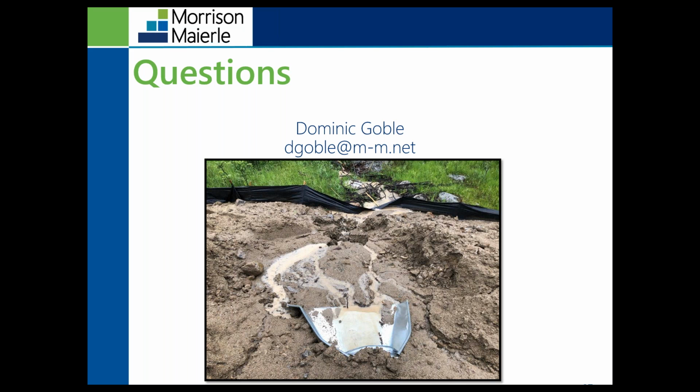So say, like in the photo that you're seeing right now where that sediment's being overtopped that silt fence, this would result in a non-compliance. It needs to be submitted to DEQ. So as part of that non-compliance report, you have to identify how you're going to ensure that this non-compliance doesn't happen again. DEQ doesn't necessarily come out on a compliance inspection as a result of non-compliance.